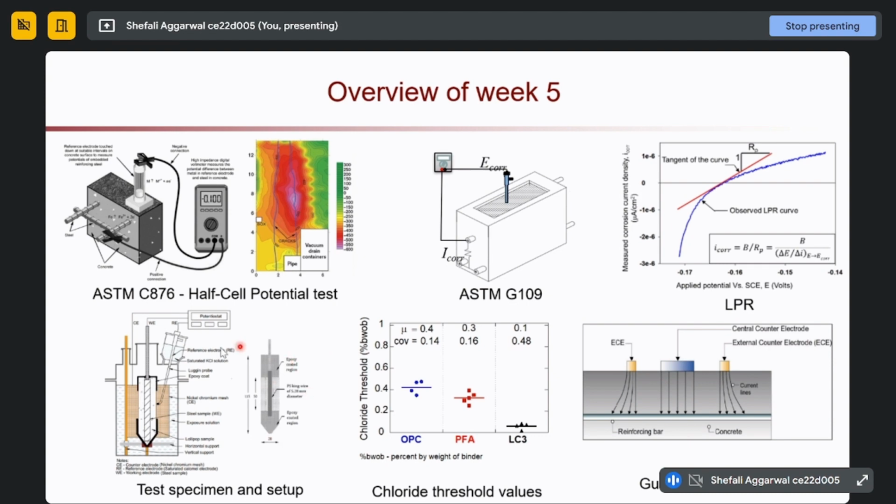So this is an ACT test which was developed in IIT Madras. All these test methods which have already been developed are mostly for metals in solution. So if we come to concrete systems, we have a home-developed ACT test where we are using rebar and mortar. We call them lollipop samples, and we use a simple three-electrode test method, where our rebar acts as the working electrode. We will use a reference electrode. In this case, we are using a saturated calomel electrode as the reference electrode, and for the counter electrode, in this case, it is nickel mesh.